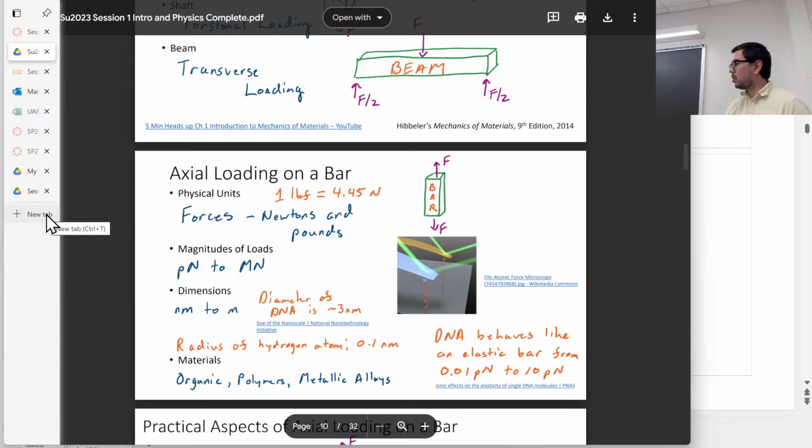And which way do the bubbles go? Well, they go against gravity, right? They don't go to the outside because they're less dense, just like soda pop, so they come to the middle. All right, so it's pretty cool. So we worked on using this form of centrifugal forming to move the bubbles to the middle and get them out. They also dissolve into solution, it turns out. So you have two ways of getting them in and out of solution, either by applying vacuum to make them bigger, to get them out, and then they can expand and travel up, or by pressure where you pressurize them in.